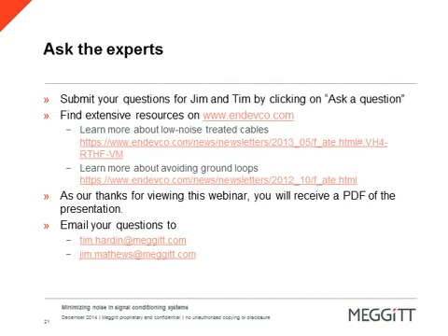Tim, I might add also, I don't know if the question is relative to a highly noisy environment with an industrial application, but that could warrant even a specific design that might have a 3-pin connection where you have an internal Faraday shield. We didn't touch on that too much because we weren't getting into the industrial applications, but that might be warranted.